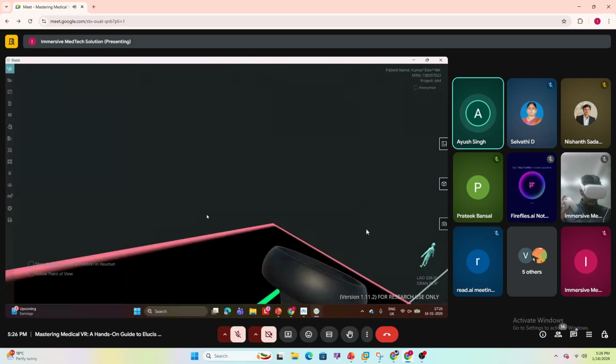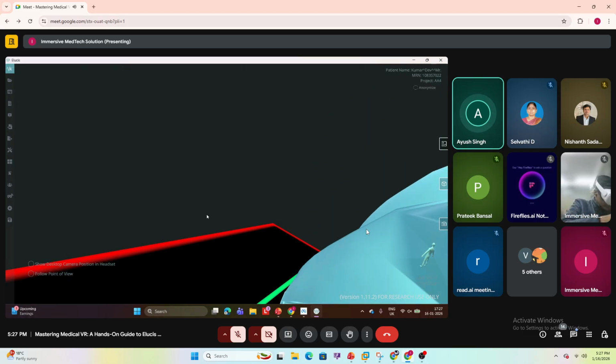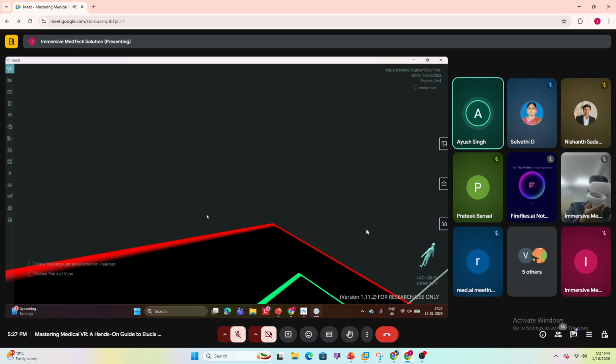Apart from that, if we need to do a free design, how do we do the design? Here we have a design option. Here we need to click on edit. Once we have clicked on edit, we have an option of create new. Here we can start designing right from scratch. Any primitive shape can be selected, for example a rectangle prism. We can also set dimensions manually.